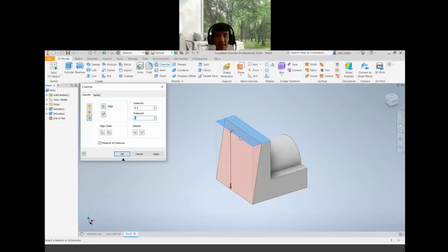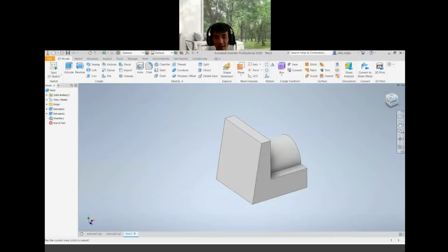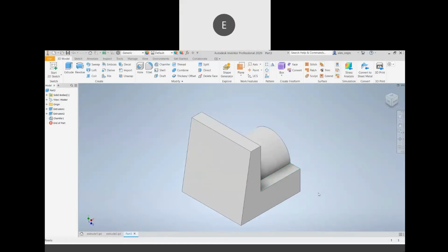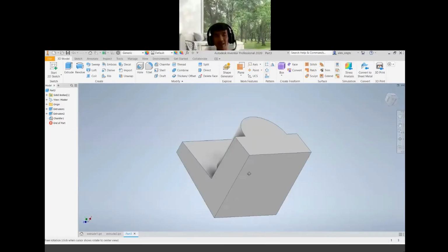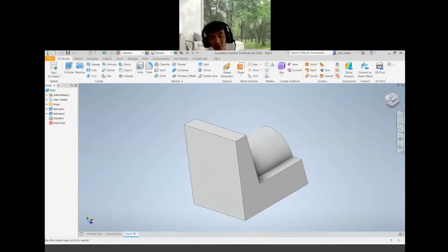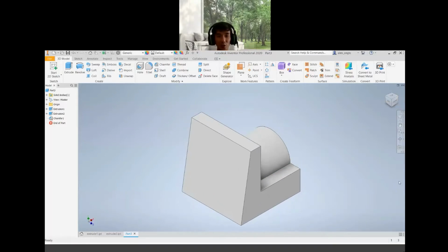Okay, next one, you need to provide the dimension. So first of all, go to dimension. Once you click on a circle, the default setting will always be the diameter. So the diameter in this case will be, what's the value? 1. 2. Radius 1, right? So diameter will be 2. But if you want to change from diameter into a radius, right?